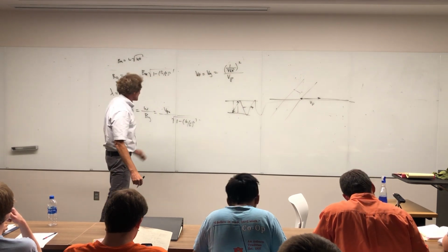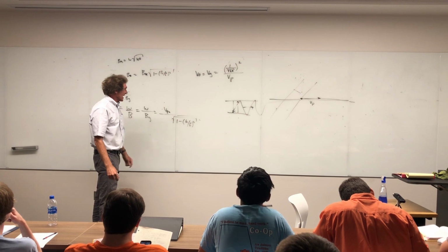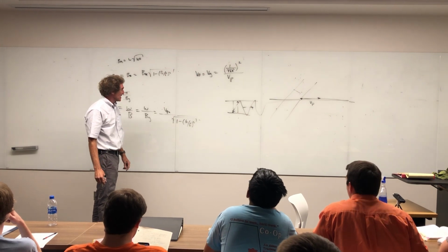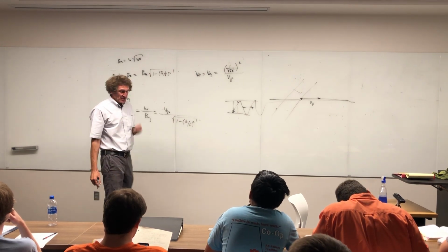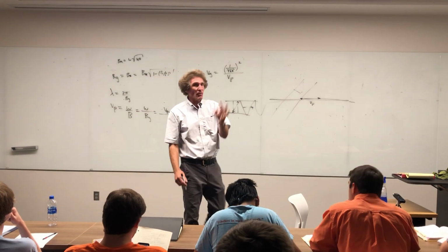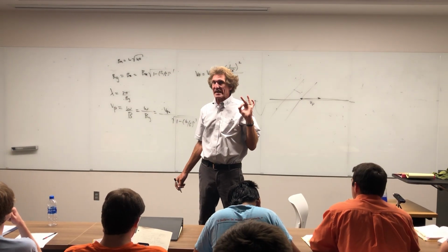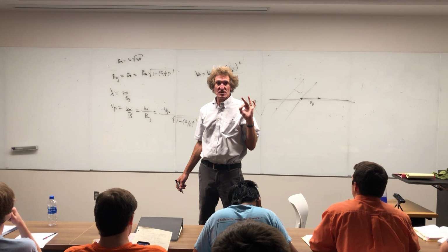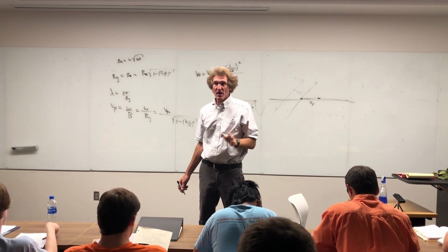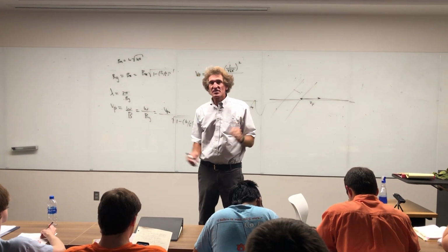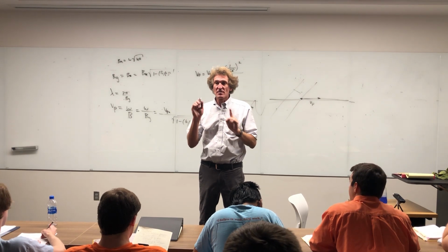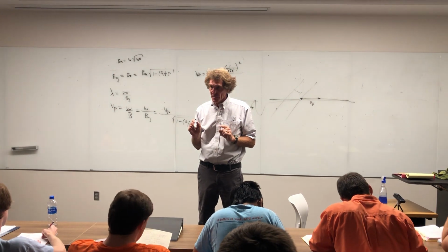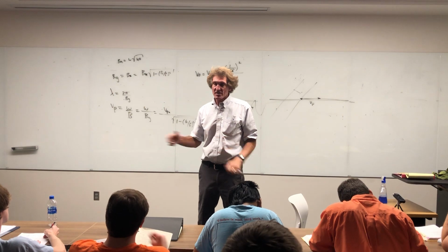So you would put this equation in there, and you're going to find out that the velocity of energy propagates at 0 meters per second at cutoff, but then it approaches the velocity in unbound media as frequency goes up. Last thing, both phase velocity and group velocity become the same thing at high frequency, as you get much, much greater than the cutoff frequency. I'll leave you go there.